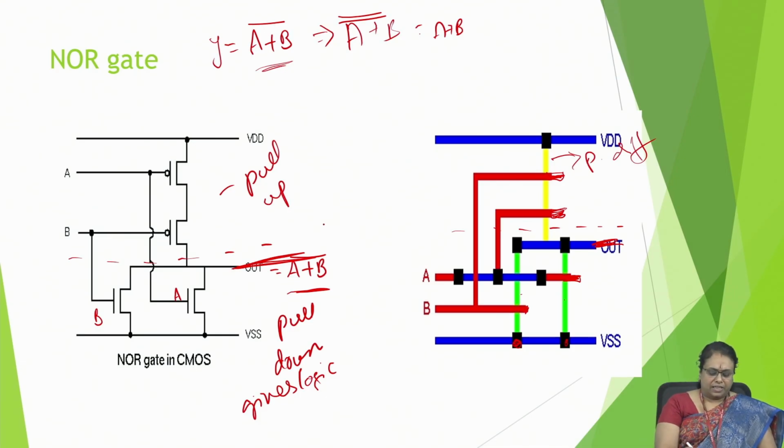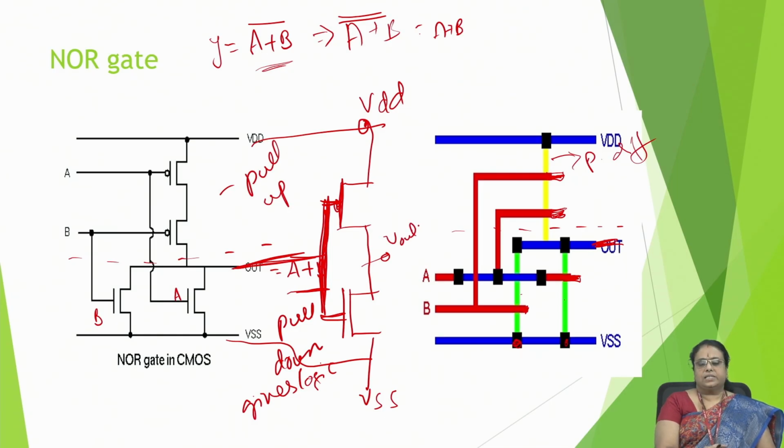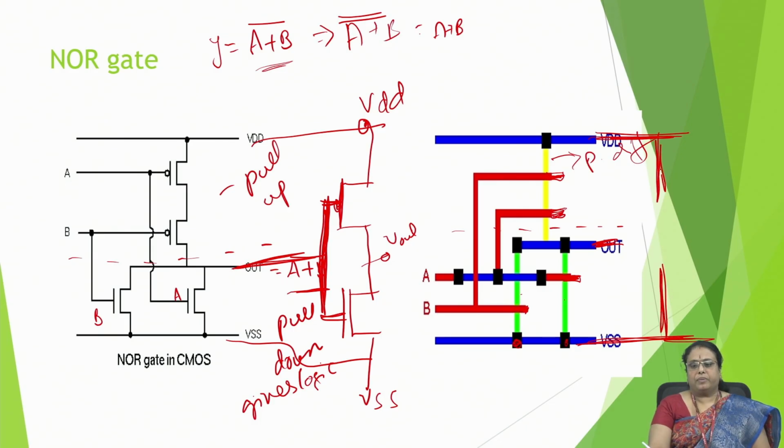And how do we generally represent the inverter? The inverter circuit will be: here we'll have the PMOS, here we'll have the NMOS, and when we attach them and connect this to VDD and this to VSS, this is our inverter circuit, and here we take Vout. This is the general schematic for the OR gate. So just adding an inverter converts this schematic diagram to an OR gate. And similarly, here we'll draw the stick diagram, extending these here and drawing another N poly here, P poly here.